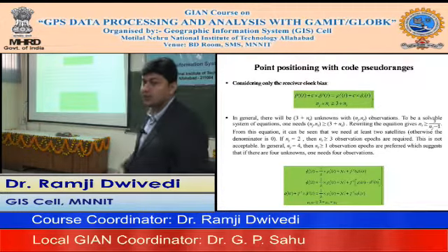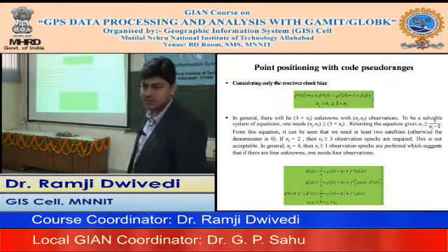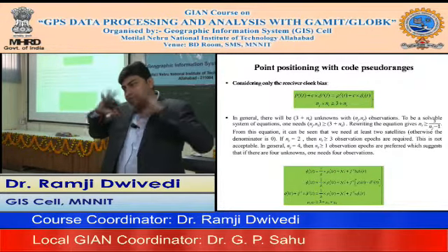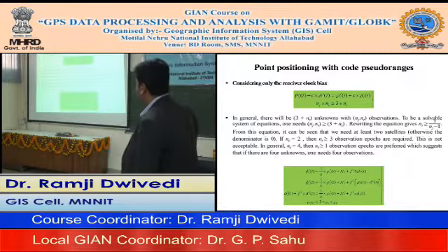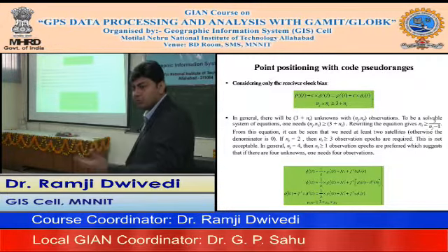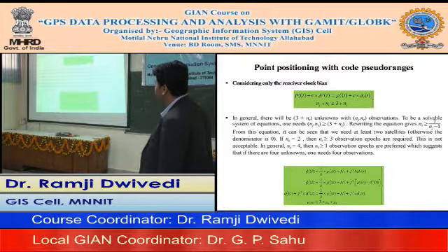And as I said, in order to favor our satellite geometry, we don't prefer to have more epoch observations from the minimum number of satellites. We want our satellite geometry to be widely spread in space, so that we don't get biased in the observation. So Nj equal to 4 is a fairly straightforward solution, where epoch 1 eventually gives the unique solution, and we can move with more epochs to get redundancy in our so-called least square solutions.